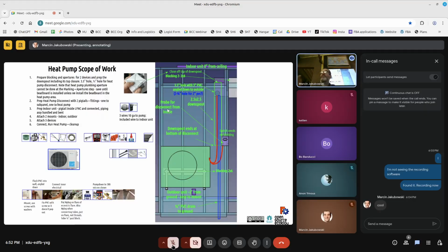However, before you do that, you have to evacuate the interior unit because you have air in there from the factory, air or nitrogen, but you need the refrigerant to displace all that volume. It has to be only refrigerant, so you have to use a pump, a vacuum pump like here.